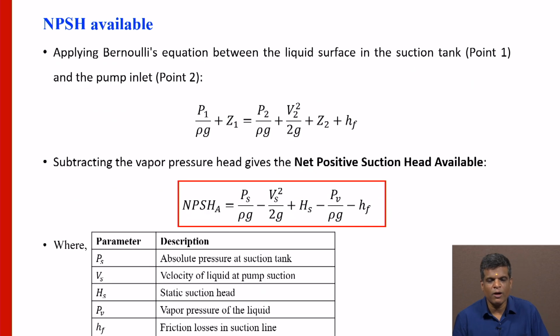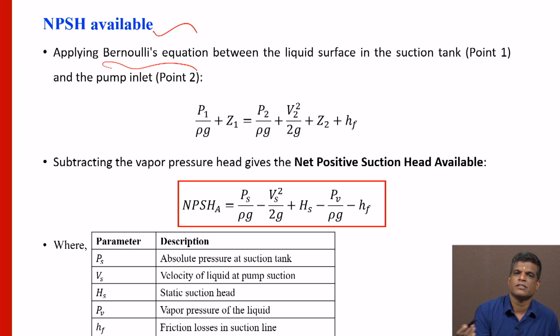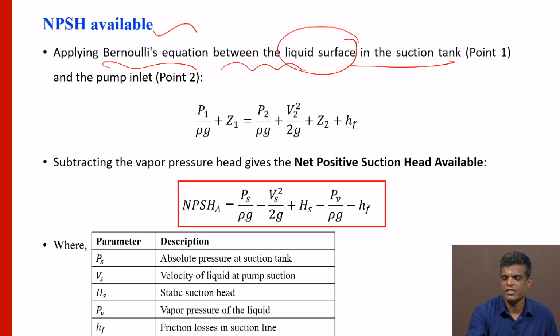Then we apply the Bernoulli equation for the NPSH available here. We already discussed this in week 3. So, what is the Bernoulli equation here? The Bernoulli equation between the liquid surface in the suction tank, point 1, and then point 2.